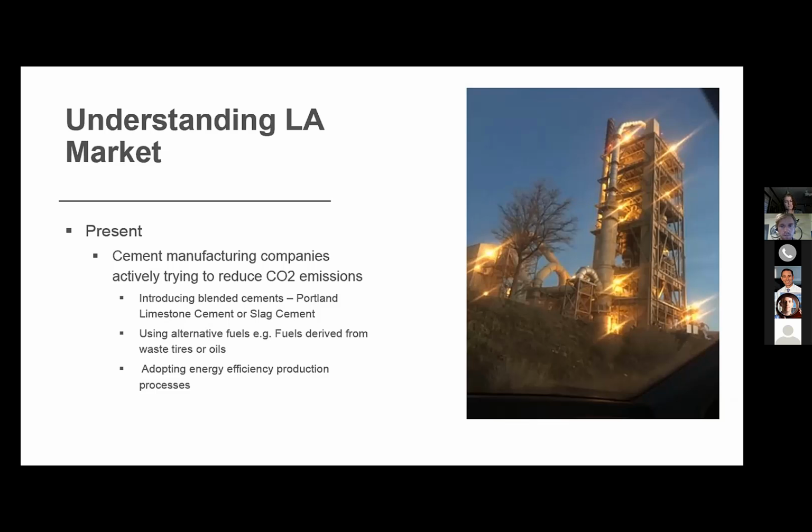So they're doing that, but it goes back to the plant capacity, right? Okay, you've got your normal cement, now you've got 1L cement. You might have type 3 cement for high early strength, you might have white cement for architectural, you might have slag, fly ash. You're talking, okay, that's 5 silos. Again, we're back to the 1960s plants that don't have that capability. So it just takes time for the capital to come through on the budgets to get these improvements on these plants. And some are doing it. I know many people are adding additional silos to their plants.